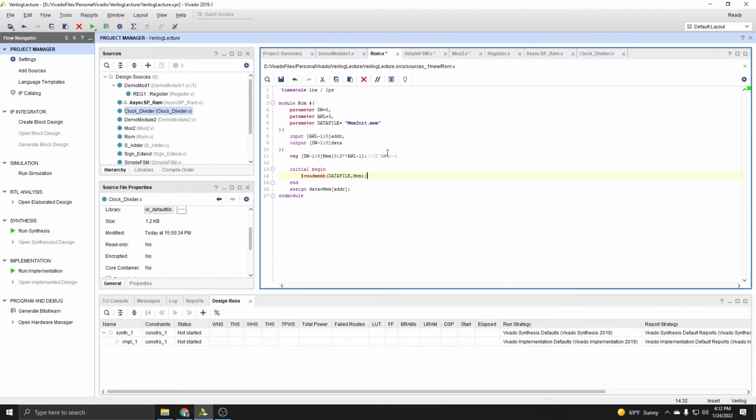In this case, I have 3 bits, so it's only 8 locations. And readmem will try to find 8 values of the size provided. In this case, it's 8 bits, so it's going to try to find 8 sets of 8 bits to fill the memory with.